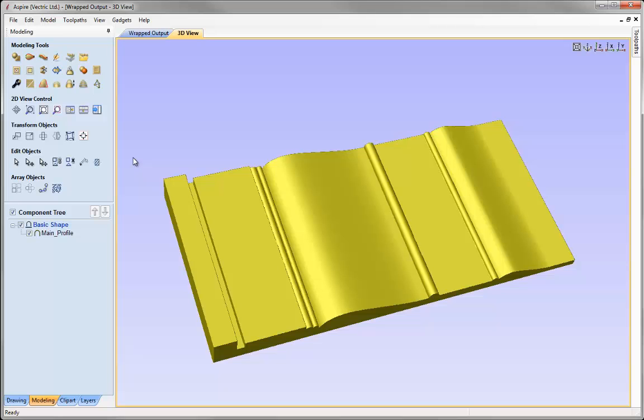In this case though, we have a number of areas on the part which will effectively create a flat surface. So at the bottom here, in this area, and also in this groove here between where the part ends and the work holding starts. To get the best result, it would be ideal if I could create 2D toolpaths to cut those areas rather than 3D.